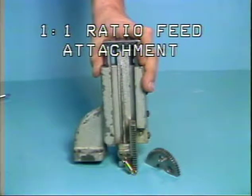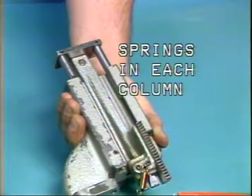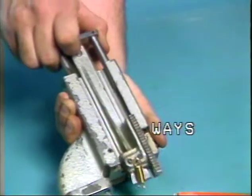This is the 1-to-1 ratio feed attachment. The maximum length of feed using the 1-to-1 ratio attachment is approximately 2 inches. This is the spring return rack. There is 1 spring in each of these 2 columns. The rack slides in these 2 ways in the body of the attachment.